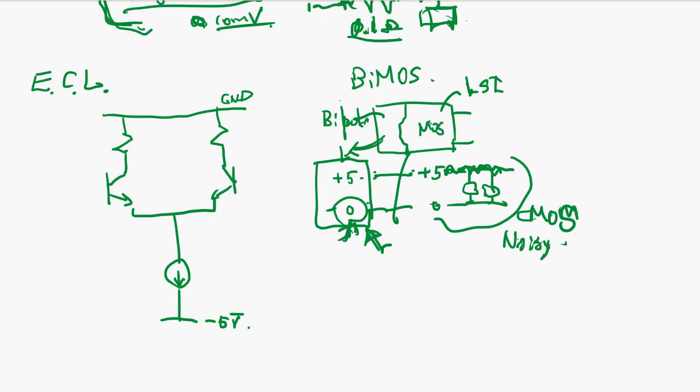And what you do is, outside the chip, through a coupling capacitor, to filter out the noise, you connect outside the chip. There are multiple chip pins for the plus 5 and the ground, so each pin has this low pass filter capacitor attached to it, so the noise doesn't get onto this side.